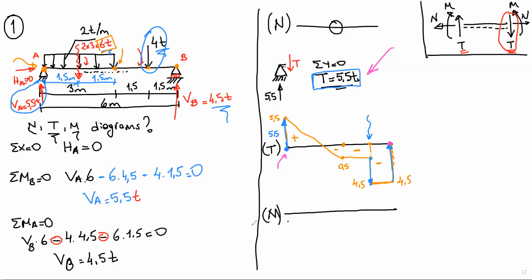Okay, what is our start moment? This location is here. The point A. Point A is in support. You know, there is two support reactions, but there is no moment. Moment is 0 at this point. That's why my start moment value is 0. Start value is 0.